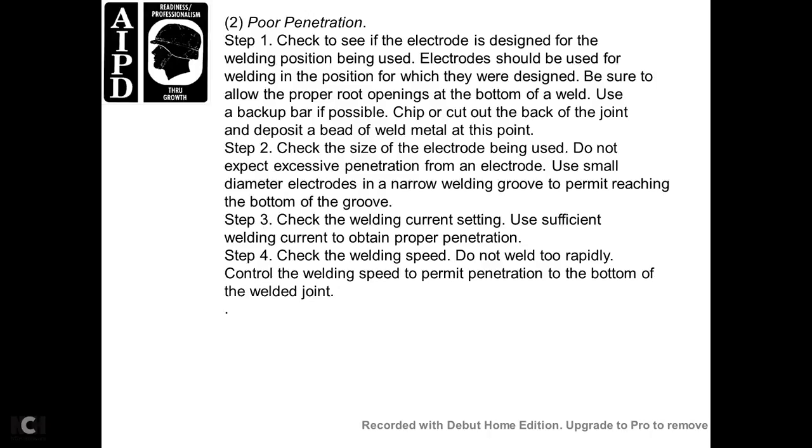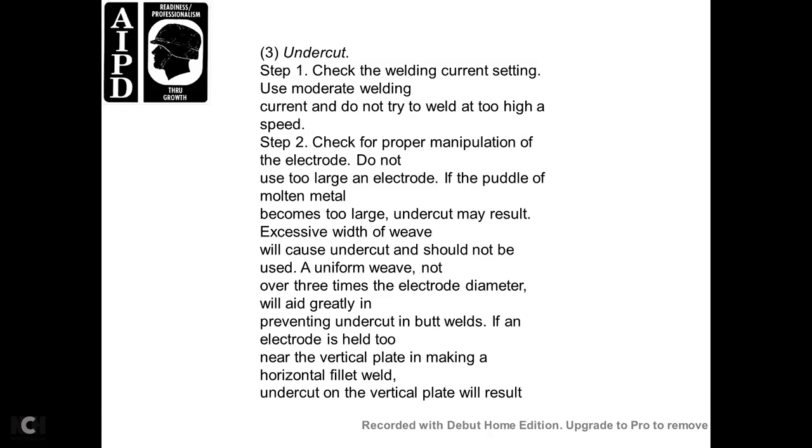Step 3, check the welding current. Use sufficient welding current to obtain the proper penetration. Step 4, check the welding speed. Do not weld rapidly. Control welding speed to permit penetration from the bottom of the joint.